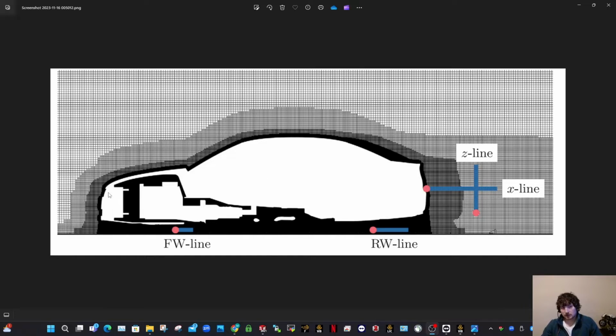So how do we do something like this in ANSYS? That's what we're going to look at today. So you can see there's a very fine layer of cells very close to the vehicle and between the ground. Then there's a less fine one outside, then it gets coarser as you move out. So we want to be able to create these layers without having to use, as I've shown you in a previous video, just boxes.